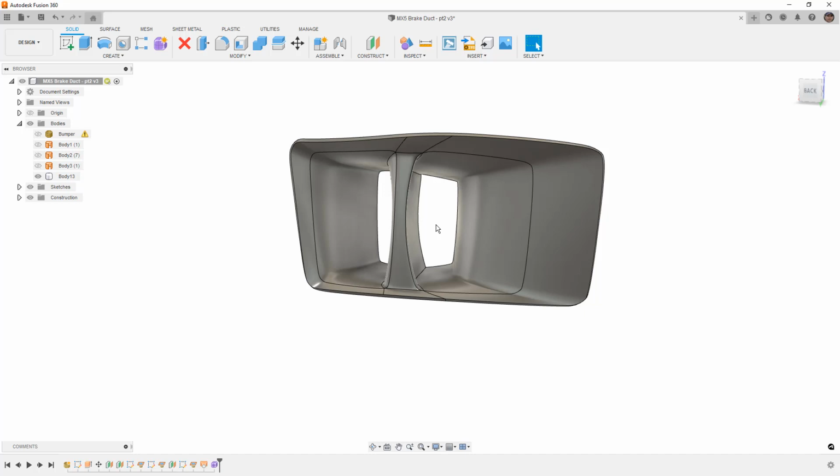It's always important to think about working with surfaces or freeform bodies that are surfaces, to think about working on just a single face of your design. Now, that could be the inside or the outside, but you have to think about it as sort of those individual layers. If you look at a part that you have laying around, when you're creating a freeform model, you're only creating either the inside or the outside of the thickness of the part. That's a concept that really needs to kind of stick with you when you're using that type of modeling.